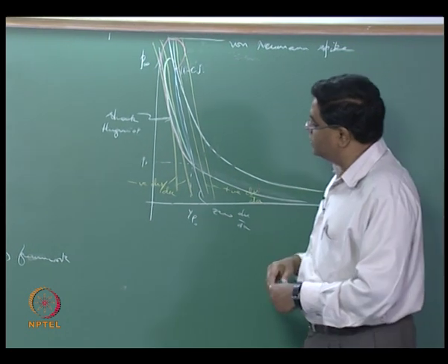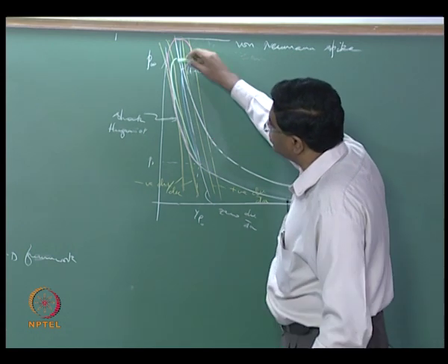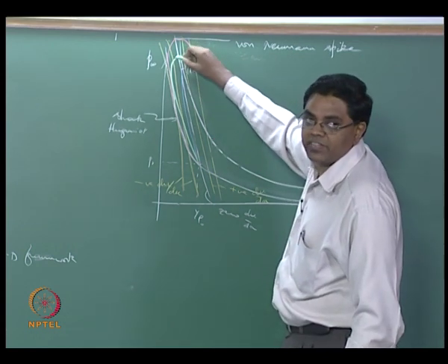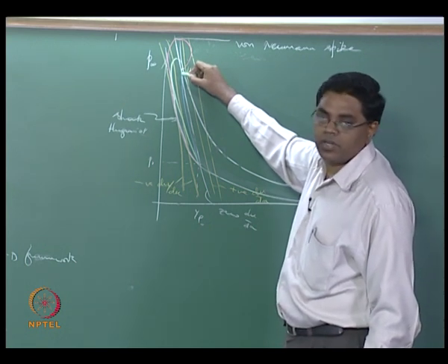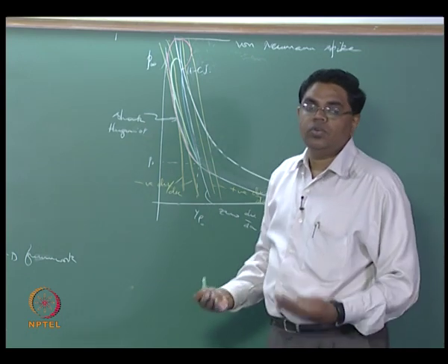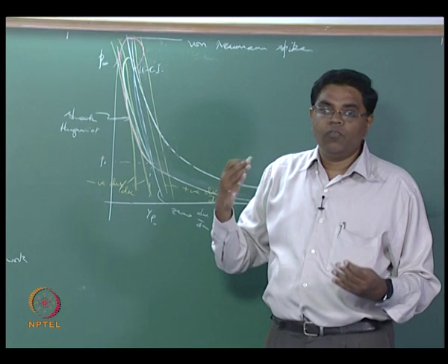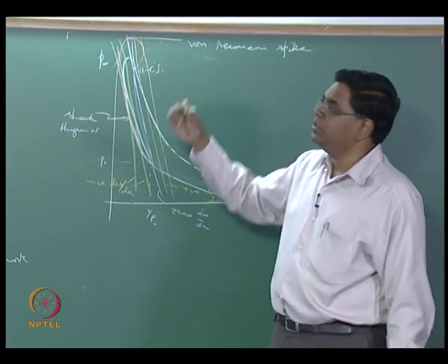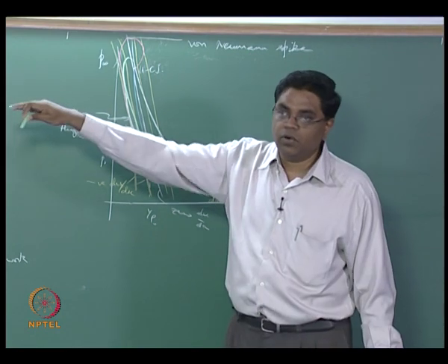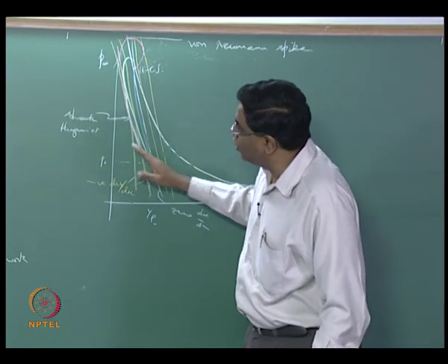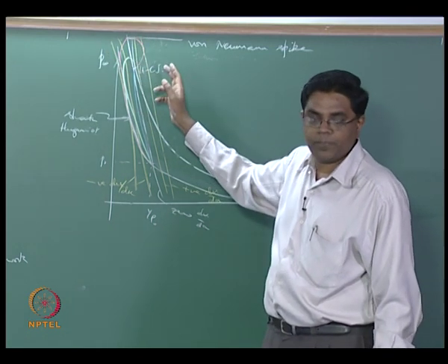Whereas if you had modestly reacting mixtures, you could still go through a pressure that is higher than the Chapman-Jouguet downstream pressure, and that would lead to something like a von Neumann spike. But the worst case von Neumann spike that you can get is with the ZND model, where all you have is a shock to begin with and then chemical reactions following that.